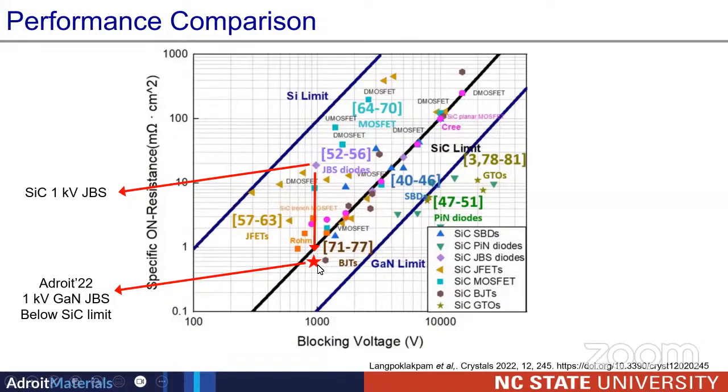So I can pass more power, or have lower losses, compared to silicon or silicon carbide devices versus my gallium nitride devices. That is the reason why we wanted to make this p-type implantation possible in gallium nitride, so that we can make better devices than other technologies.